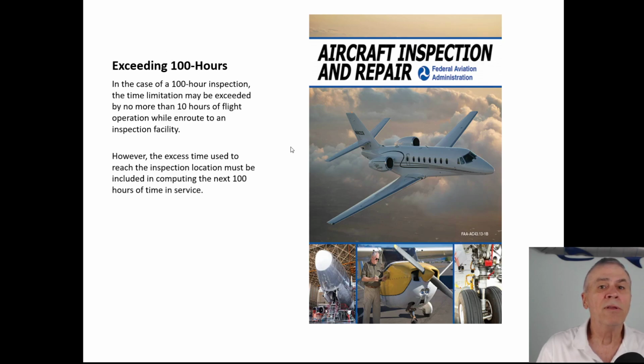They're actually talking in this one about exceeding 100 hours. And we did take a look at that when we first looked at the requirement under 43.11, because the last sentence or two did say, well, you may exceed the 100 hours by up to 10 hours for the purposes of getting to the place to conduct the inspection. And then the last sentence did say, if you do exceed the 100 hours, they shall be accounted for in the next 100 hours.